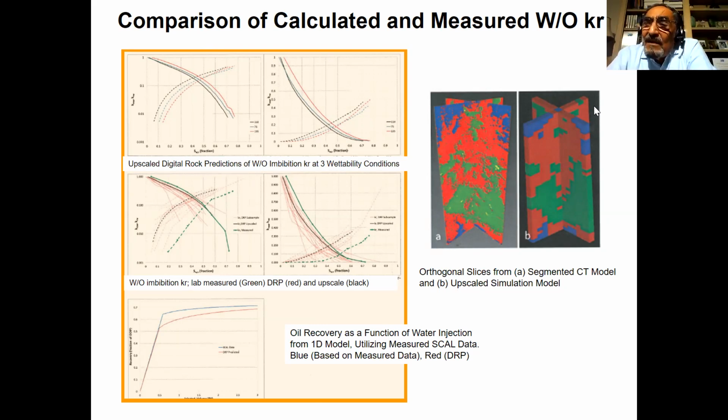The challenge is that lab studies for this type of rock are extremely hard. I did some relative permeability measurements, and when the water first goes through the rock it basically traps the oil, and the trapped oil itself reduces permeability significantly. The fracture system works as a network for relative permeability measurement, but the matrix is very challenging to treat with a regular or conventional displacement process. There is more involved in it. Probably Dr. Firouzabadi can talk about that a little bit more.